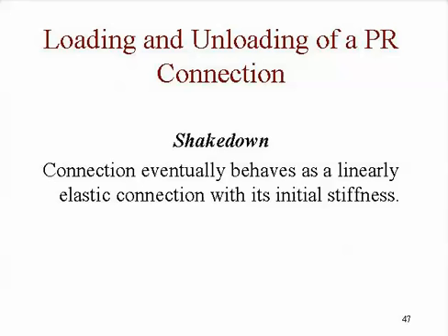Okay? But the whole idea of shakedown is that that connection, after it goes through this inelastic behavior, gets to a point where the loading and the unloading never exceeds the maximum that we already had on it, and therefore can behave elastically.